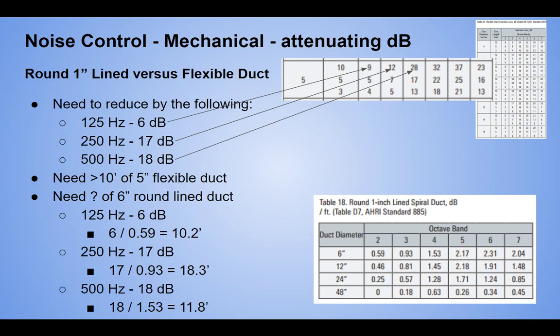So we're still 10 here, still 11 if we consider best case scenario. But if I'm doing a design, I'm going off of 18 feet right now. I want to be more cautious in case I have to give something up on there. And we've got more absorption at 500 hertz. We only need 11 feet.